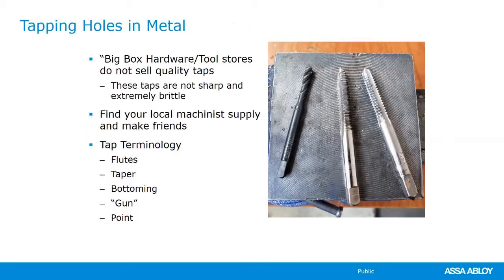When it comes to installing commercial hardware, especially if we're looking at Sargent commercial hardware, Sargent is a premium brand. They make really quality products, but you know what? They will absolutely fall off the door like anything else if you use just regular small sheet metal screws, okay?